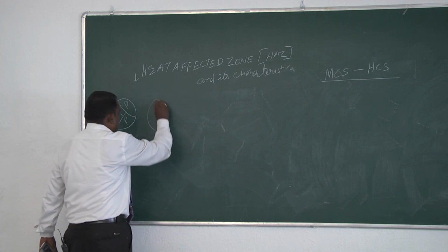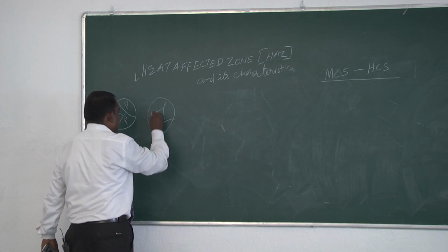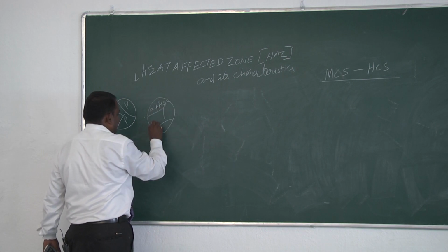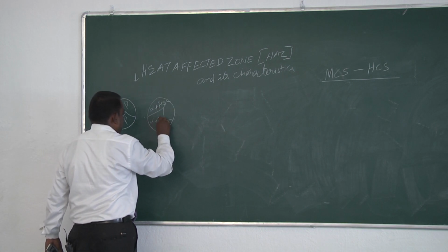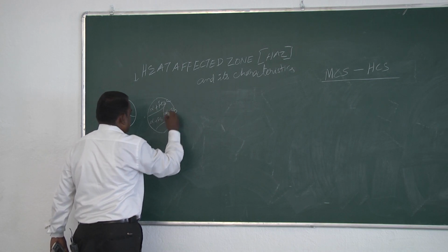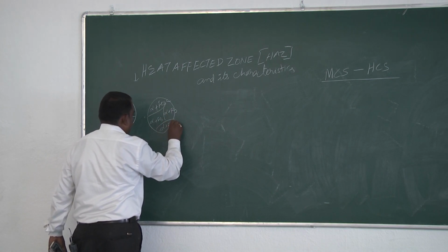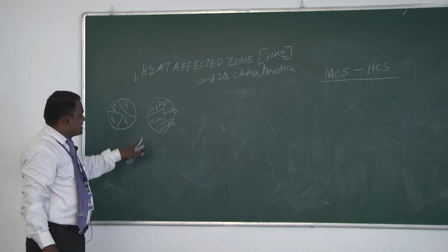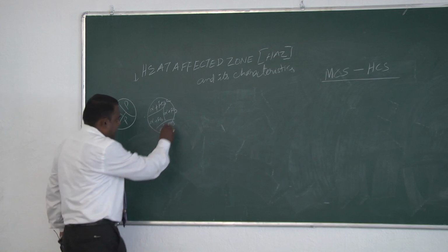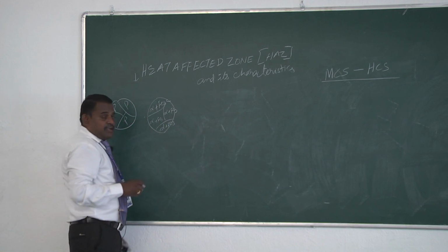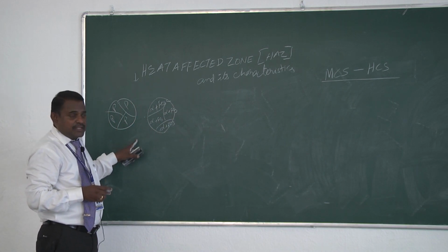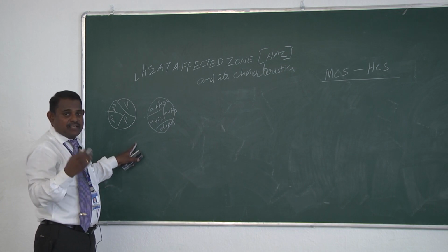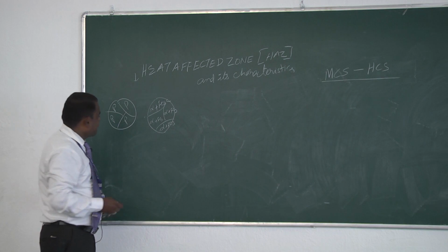That means it has alternate lamellae of alpha plus Fe3C. So even when it is heated or comes back to room temperature, it will end up with alpha plus Fe3C again in the heat affected zone. The weld metal primarily depends on the type of filler material and process parameters which I am using.